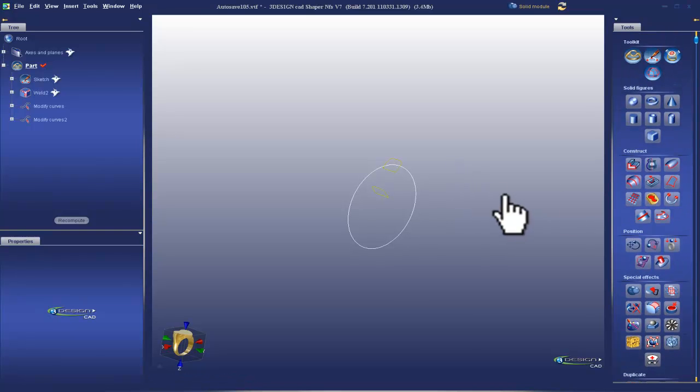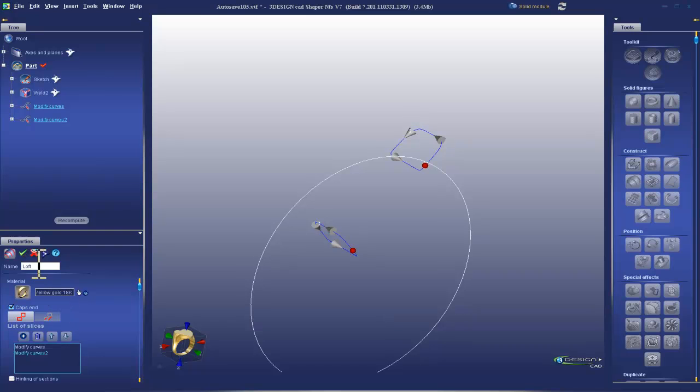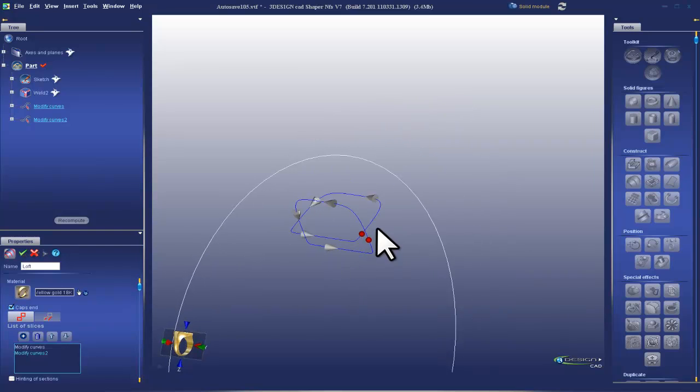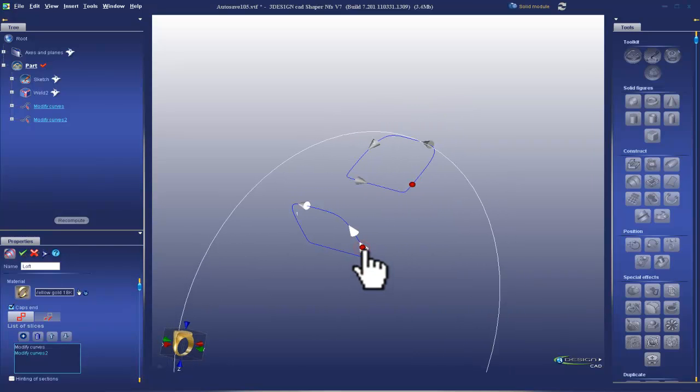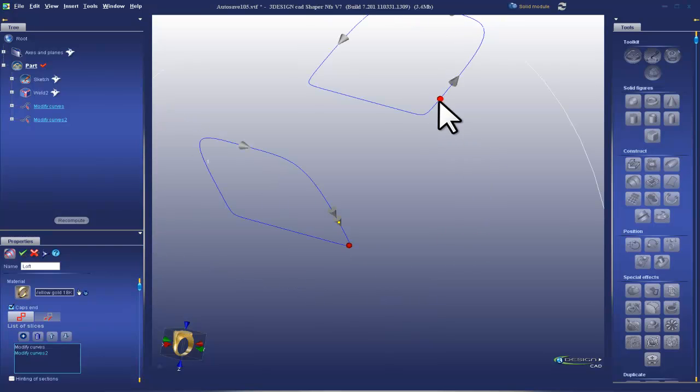Extracting curves is interesting. Extracting and deforming changes the number of control points that you have. So right now these curves are extremely heavy with control points. So lofting is a bit of a challenge on curves like this. The curves also have to be going in the same direction. See if that matches up. Nope, we're not getting the loft to take. So let's try adjusting these maybe down to there, see if that takes.